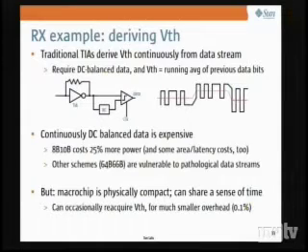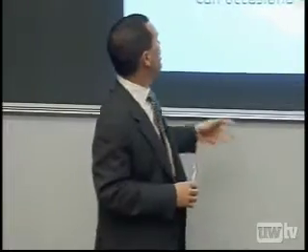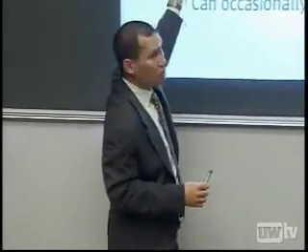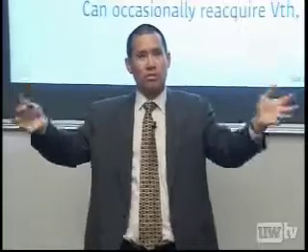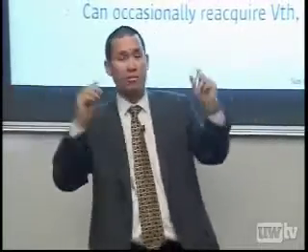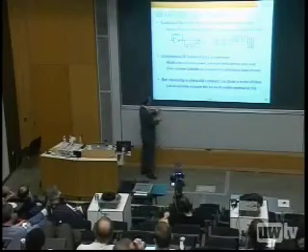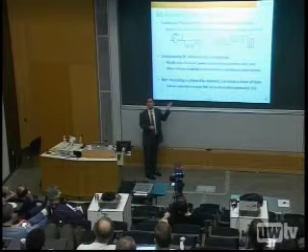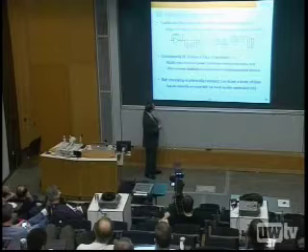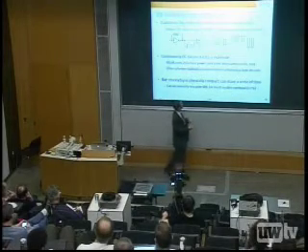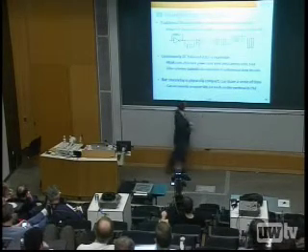Now that's okay, but I need DC balanced data for that. Getting DC balanced data is somewhat expensive, because of the traditional 8B/10B encoding, which means for every byte you send, you pack it into a 10-bit stream so that you make sure that that 10-bit stream is almost DC balanced if possible. That's okay, but it costs you 25% more power because you're doing 10 bits instead of 8 bits. Other schemes are also not great because pathological data streams can cause large sequences of errors.